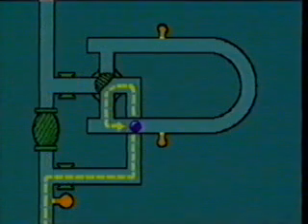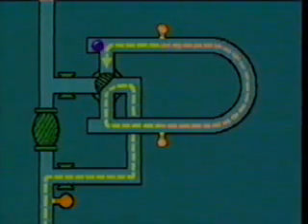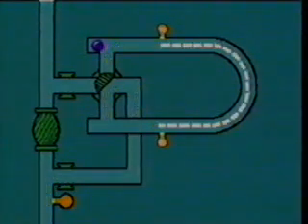The displacer in a pipe prover is typically a sphere. However, a piston may also be used. As the displacer moves between the detectors, a fixed volume of NGLs is measured. During the displacer trip, a pulse counter records the number of pulses generated by the meter.